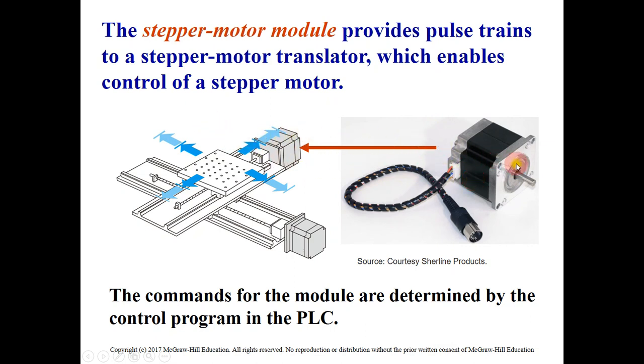This module will be the interface between the stepper motor and the PLC, sending data about the speed of the stepper motor by providing a train of pulses and updating the PLC system. This data will later be used to monitor the stepper motor or to take any control action in the process under control.